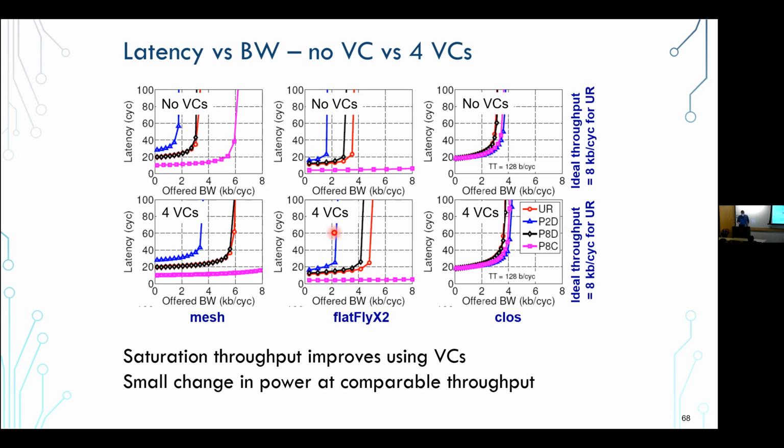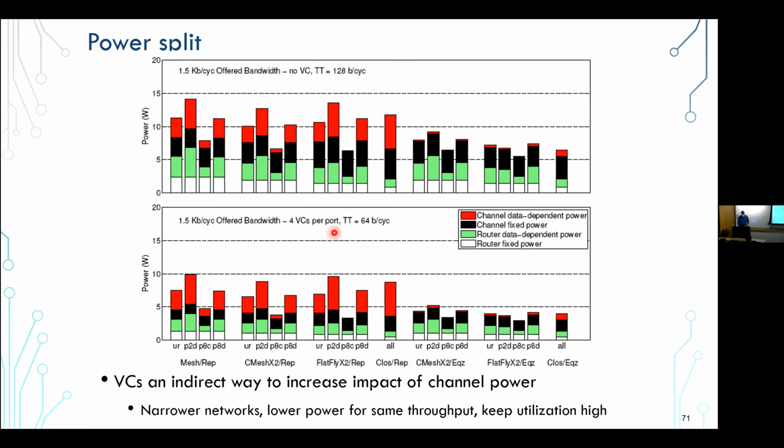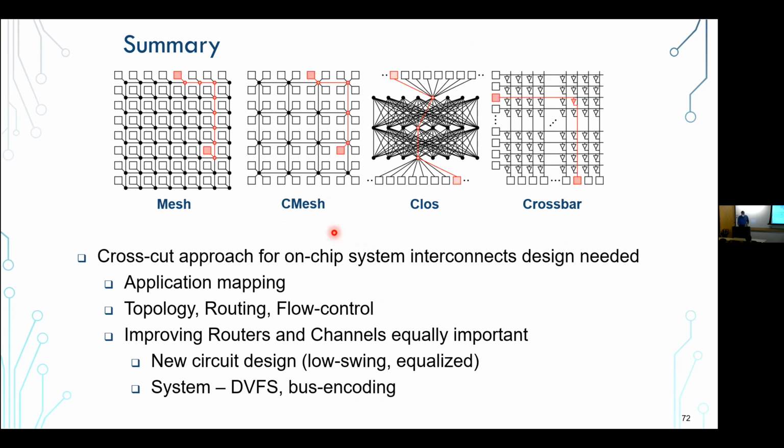So if you have enough memory to partition it, it's best to partition it into as many VCs as you can. But you have to keep in mind what your channel routing distance is, and whether you are satisfying that credit-based flow control law. Yeah, and these are some of the charts you can go and take a look at.